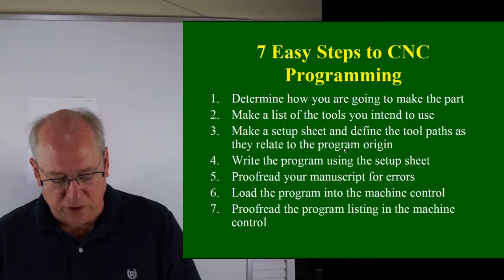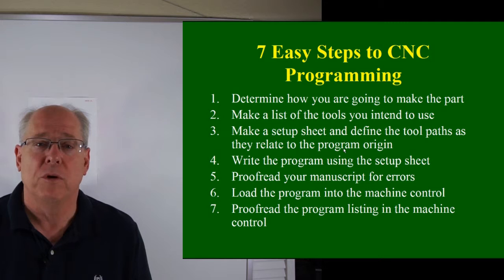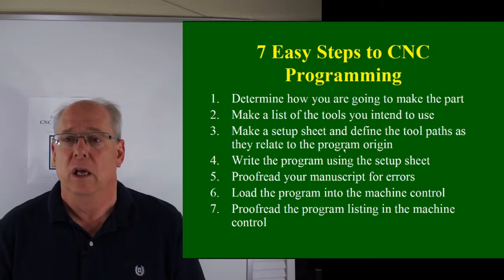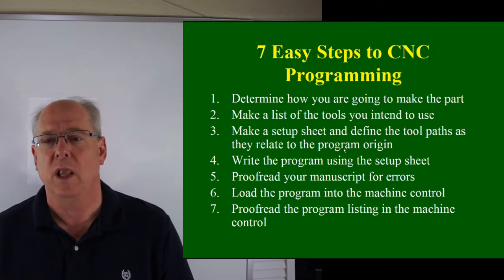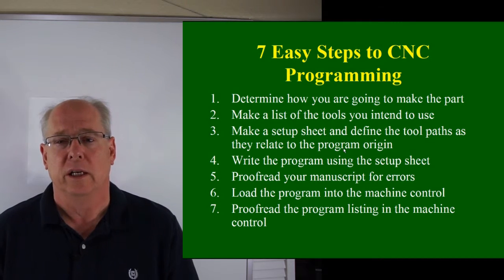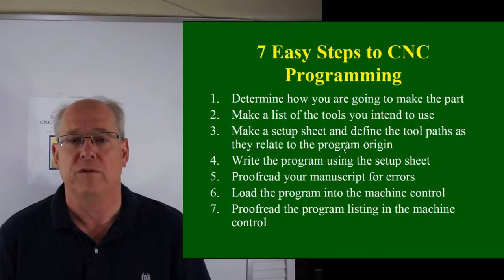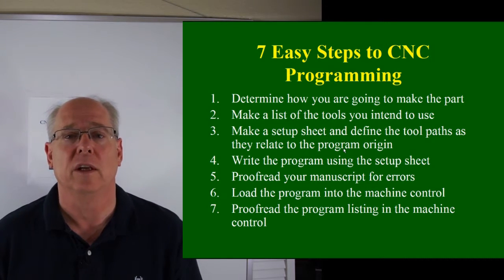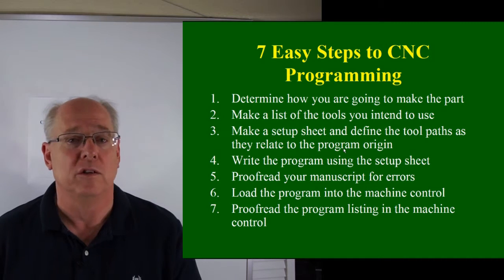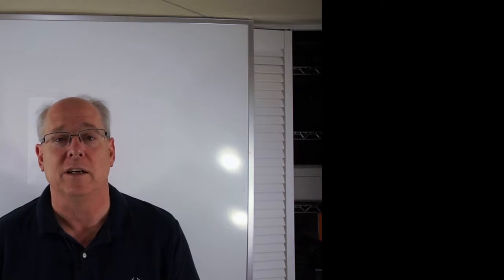And the 7th step is, once that program is loaded in the machine, you want to look at it and make sure it loaded properly and didn't drop anything. It's one last opportunity to check and see what's going on before you push the button, to make sure it's safe and nothing's going to get damaged or broken, or just simply waste a bunch of time cutting air.